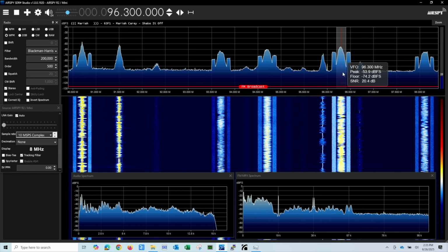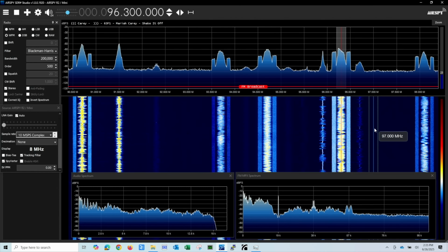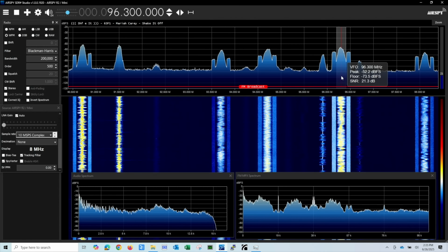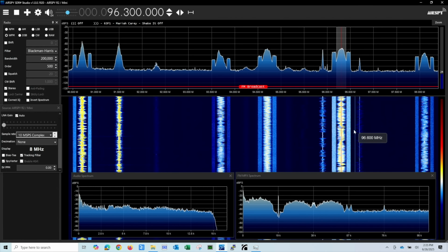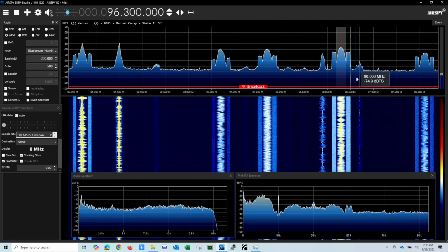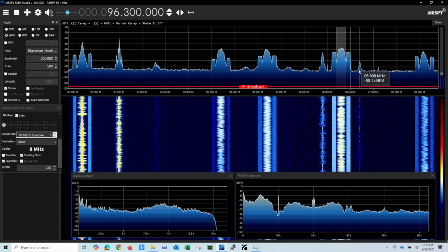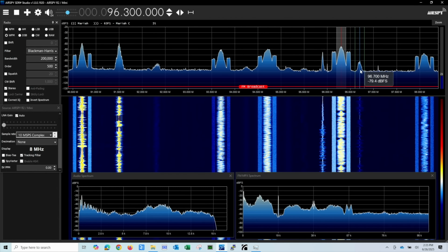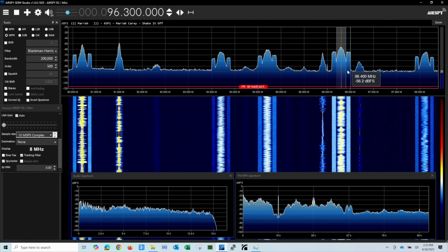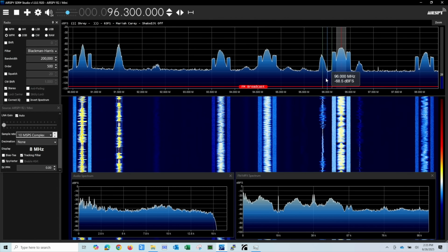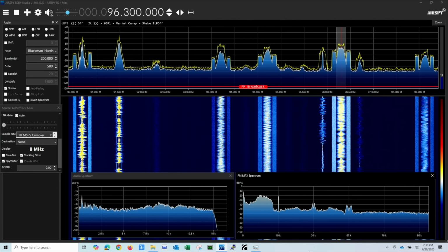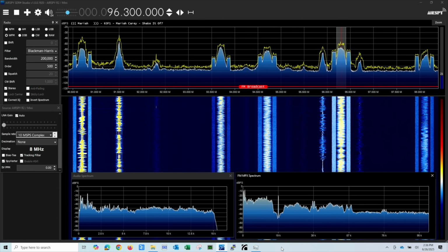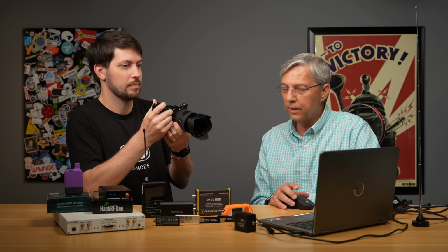Yeah, but what we look for is anything that's an anomaly, and that would include at times when the channel 96.3 was having trouble with their HD channel, and it would put out regrowth patterns from the digital carriers, and it would wipe us out right here. And I could see it easily on here, so I used to sit there, and you can right-click on this, for instance, and now I'm getting peak values, and I could come in the next day and basically see anything that popped up.